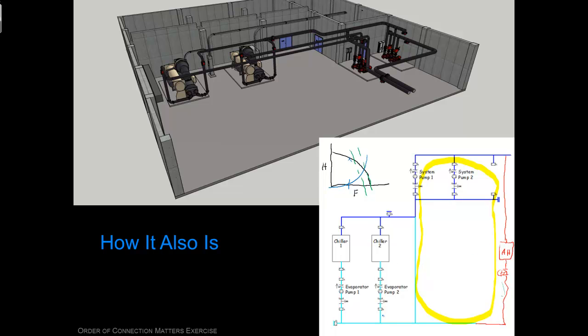The pumps basically pumped the chillers and the loads about the same amount of water all the time. The pumps had to have the head they needed for the chillers, the distribution piping network and the loads. So you had constant flow high head pumps running continuously. By going to this system design, we decoupled those two things.